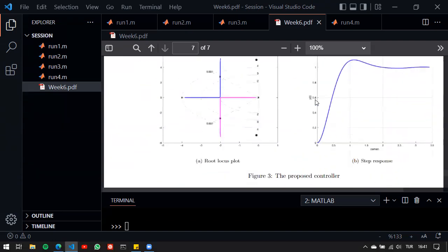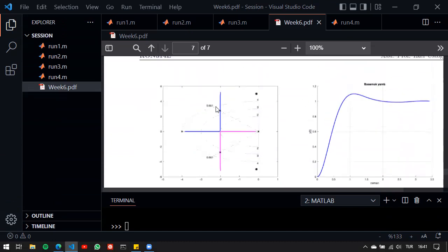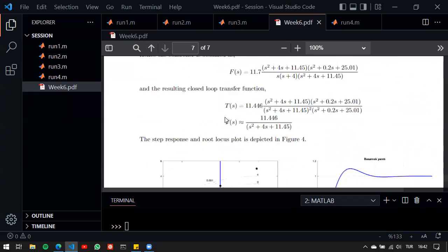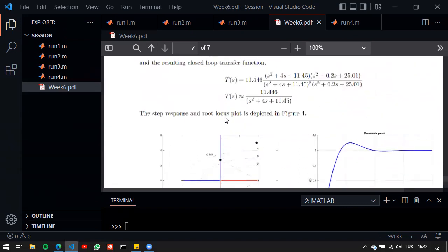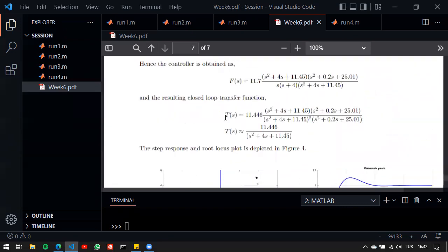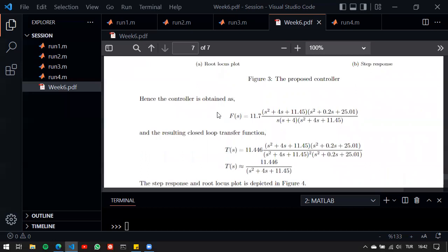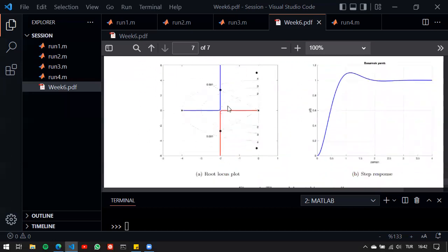And then we've also seen, based on the previous examples, that we might add one pole at -4 so that they coincide at -2 and one of them goes up and down so that we can choose the point that we are after, where zeta is 0.59, and then we have also the corresponding omega value. And we've seen that the model matching controller gives us the same results, which is not really that surprising for the system because this is the best we can do.